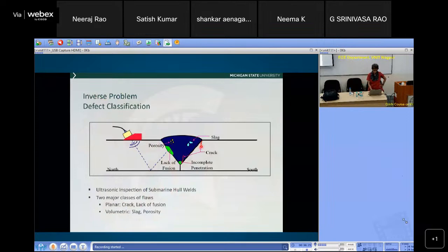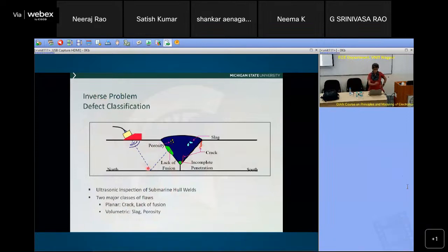And we saw that you actually do a raster scan on one side, because you don't have access on both sides. You will have the ultrasonic going in there and coming back. Sometimes you've got to make sure that ultrasonics can come back from here. It can go from here to the back wall and come back. There are people who are in communication, you know what multipath travel is. It's the same thing with ultrasonic. So in interpretation, you've got to keep all that at the back of your mind.